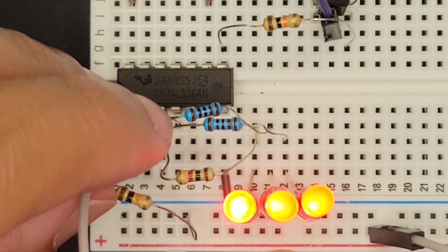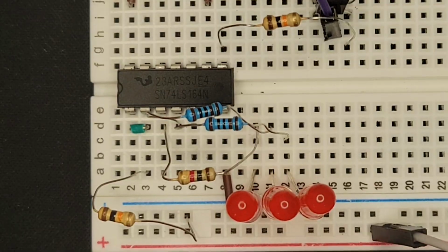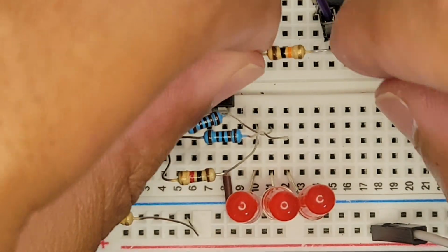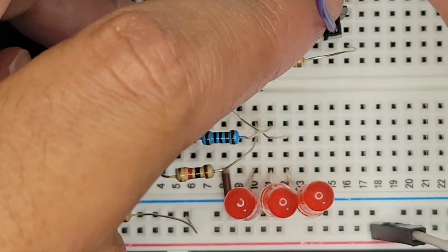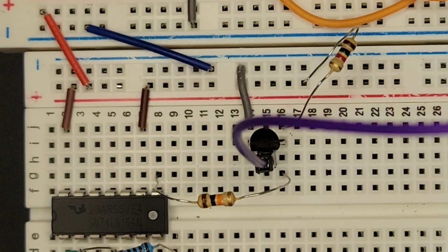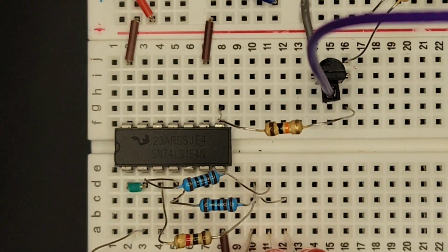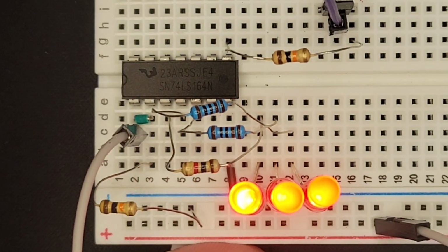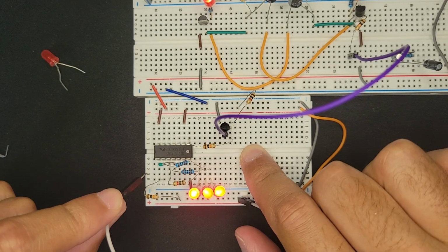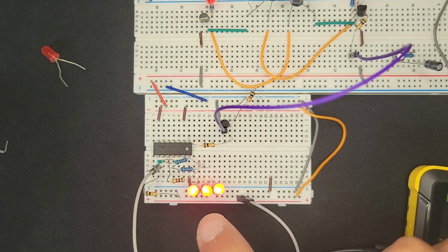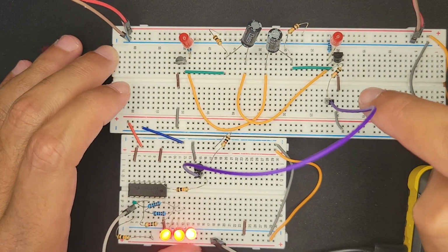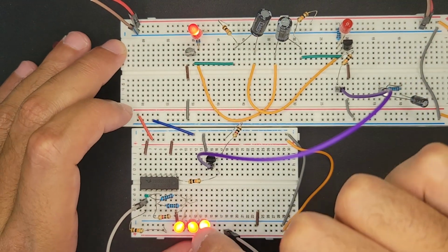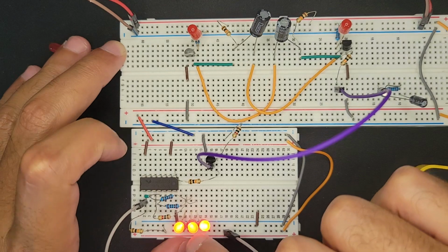Ooh, I don't like that. What just happened? There's definitely some double clock impulses happening. Maybe I do need to clean up the signal more. Damn, thought I was in the clear. Let's see. Next impulse turns on all 3. Definitely some weird bouncing going on, I think. The clock signal is not clean enough after all, it seems, because it's pulsing many times, almost instantaneously.